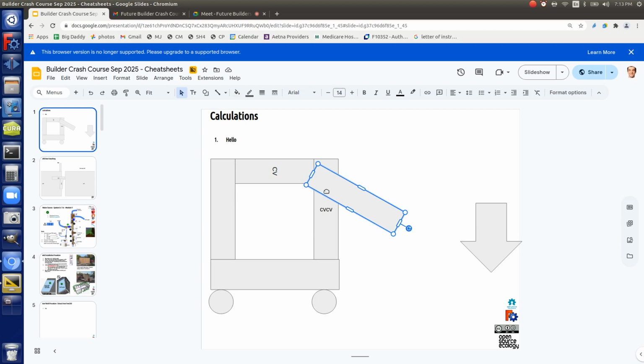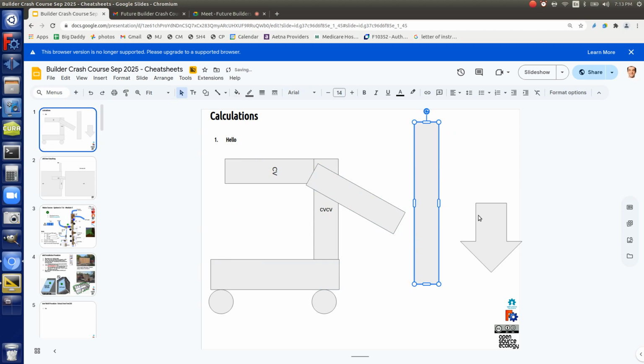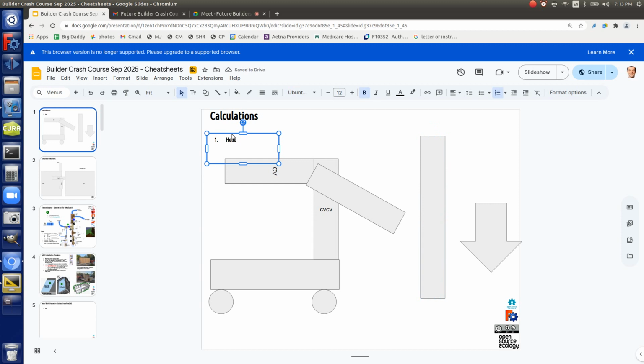Okay, these are all kinds of things you have to consider when you get into the process of designing new things, and I'm just going through a few here. I didn't get into how far off vertical a wall can be. Let's take a look at it. You've got an 8-foot wall. Say it's a 2x6 wall, so it's 5.5 inches. This will tell you the basic analysis for what's acceptable. So when you're building, you don't have nightmares like, is that going to fall down? Because you can assess what's going to happen.